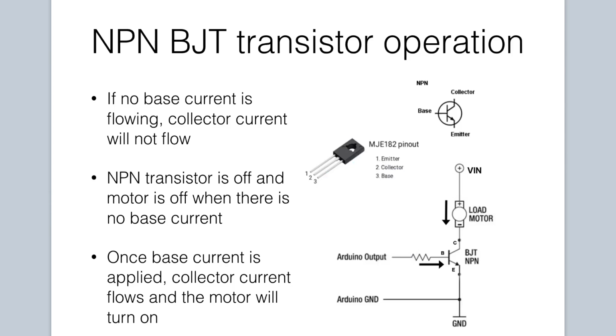We are actually incorporating pulse width modulation as well to also control the speed of the fan. The longer the on duty cycle that is applied, the faster the fan spins. We will see this in more detail later on when we examine the code.